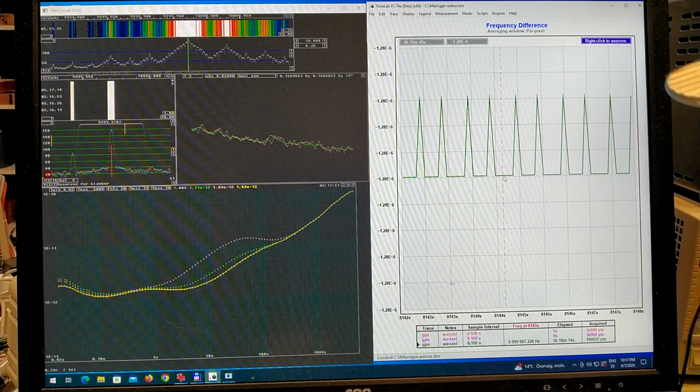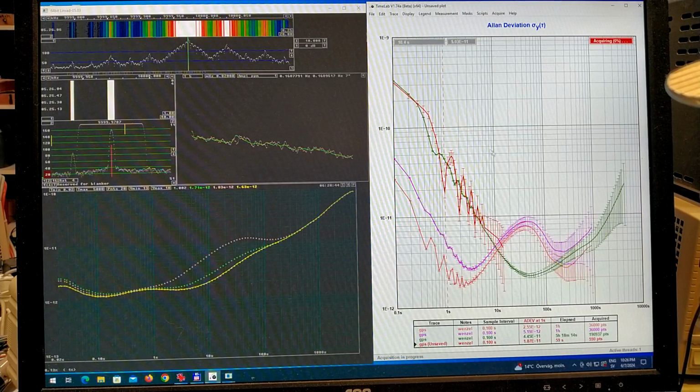the frequency at the flat place here is 7.220 as the last numbers, but on the peak it says 7.230. That's 10 millihertz. That's a very high jump in the frequency. Here I have started a new measurement, the red trace.